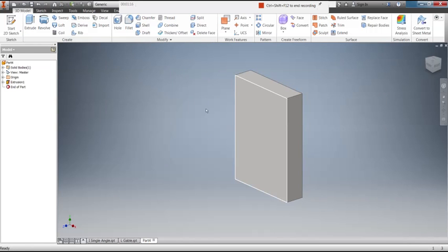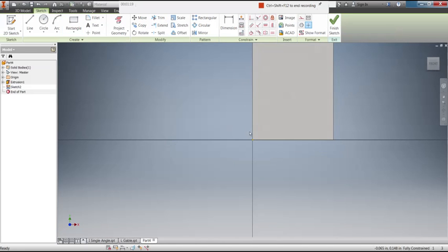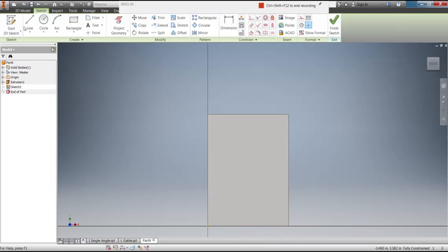Next I'll draw the windows for the front. So a sketch on the front. Similar to the other windows, they're going to be 3/16 inches wide. And it looks like I'm going to make them 11/16 inches tall. So I'll start with my lines here. Make those two sides the same. Make the width 3/16. From the edge, the window is 3/8 away, and from the bottom it is 1/4 of an inch away. So I'll do it 1/4 here and 3/8 here.